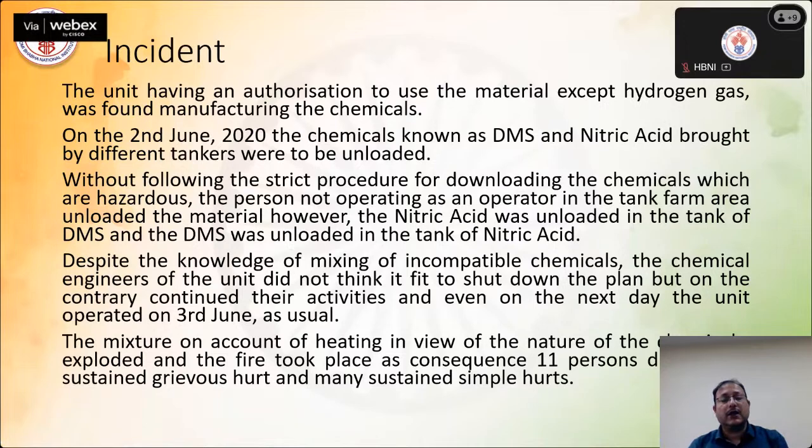So you can see the fault here itself: both are incompatible chemicals. And even if they were not incompatible chemicals, the storage SOP says that you cannot store a material inside another material's tank. You have to fill the tank with the same quality and material.